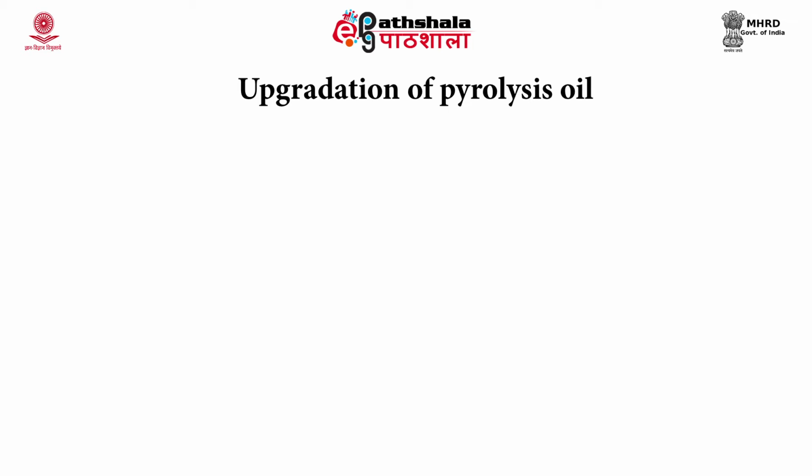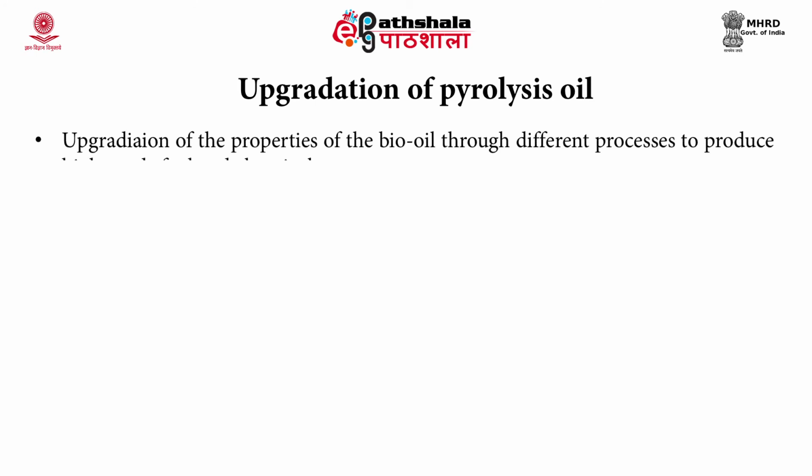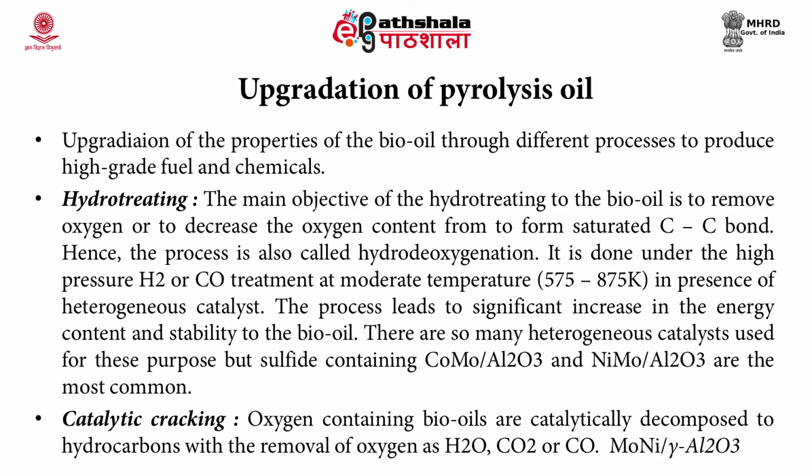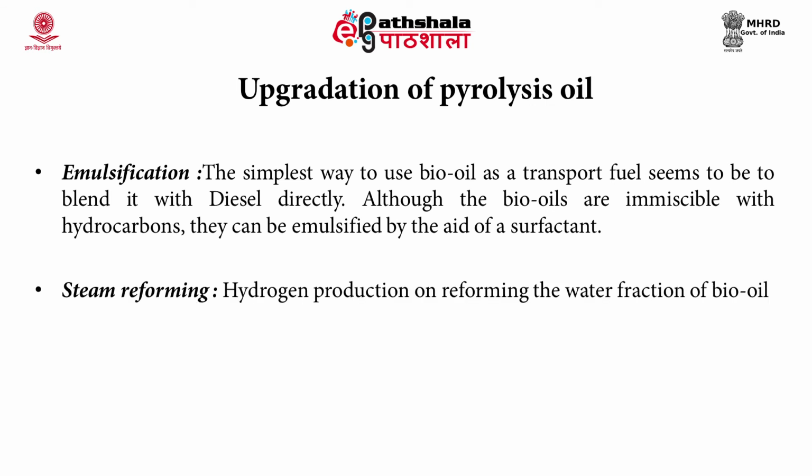So, it is thermally unstable and can undergo secondary reaction to yield high molecular weight polymers. We have seen the limitations. So, in order to upgrade the properties of the bio oil, there are different processes to produce the high grade fuel and chemicals. Some are hydrotreating, catalytic cracking, emulsification and steam reforming.